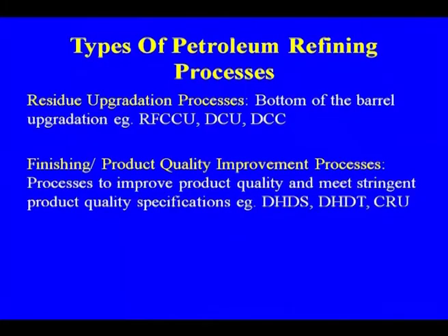Then there are the residue upgrading technologies, bottom of the barrel upgrading, that is the residue fluid catalytic cracking unit, where the heavier fraction, and deep catalytic cracking units, DCC, all those things, for upgrading the residue which you are getting there.